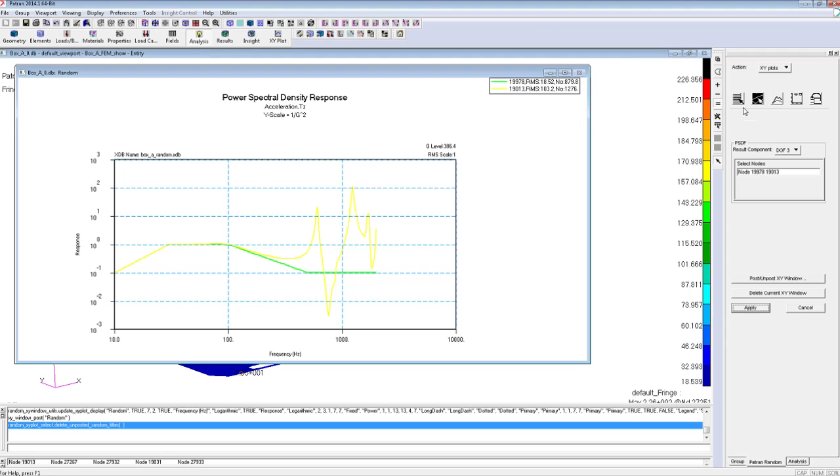We are looking at accelerations. The accelerations actually come up to 1, but most of the time they're about 0.1 or so over most of the frequency range. Something like that for input PSD is relatively common. The other point I picked was on the circuit board post, and we see some sort of magnification there. Fortunately for us, that magnification doesn't happen until much later in the frequency range, so that's a good thing. That's the perspective of a very heavy, very stiff box. Maybe things just work out this way.